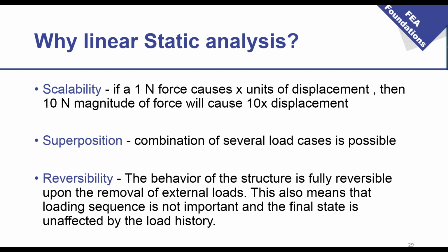I was talking a bit about superposition, so you can make a combination of several load cases, and you can even make a combination of the analysis cases. And the third feature you can also get information about is reversibility. But this is basically related to the loading sequence. So in this analysis, the loading sequence is not important. The final state is always the same and is unaffected by the load history.